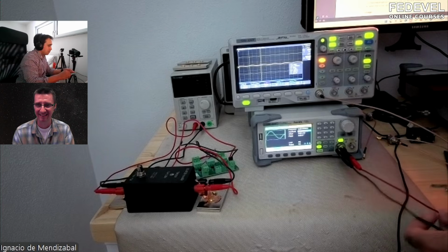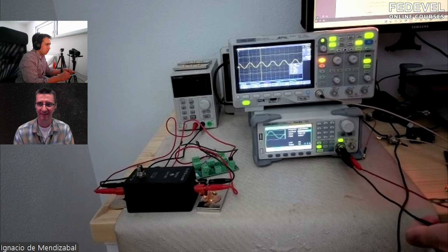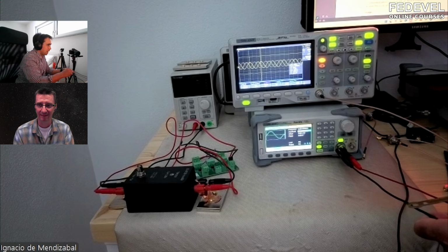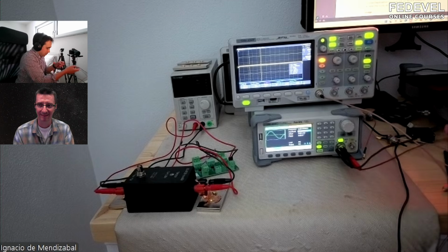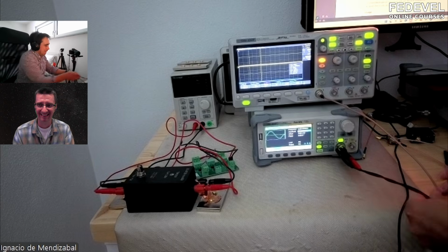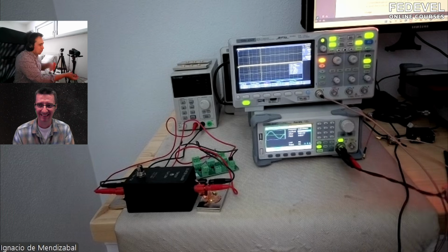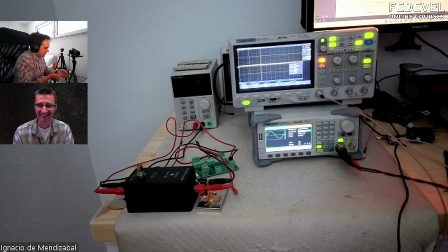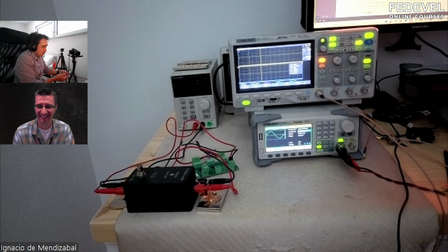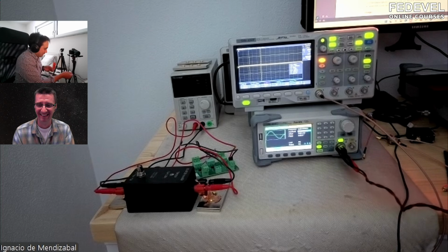So let's do it. I am measuring on the positive, and I am seeing this. I am measuring on the negative, and I am seeing this. So Robert is asking what happens if I twist the cables. You hear somewhere that twisting cables is beneficial for EMC. I don't know if it's a benefit; I would like to know. I never measured the near field of a twisted cable. So let's see.